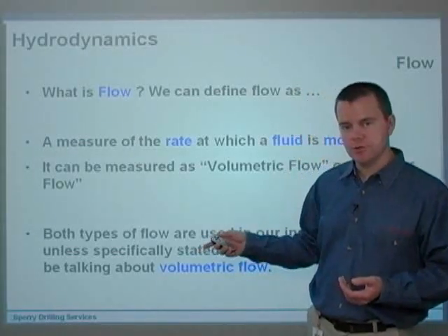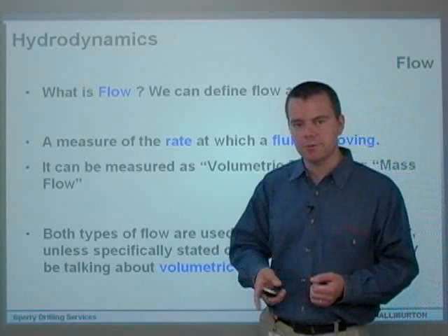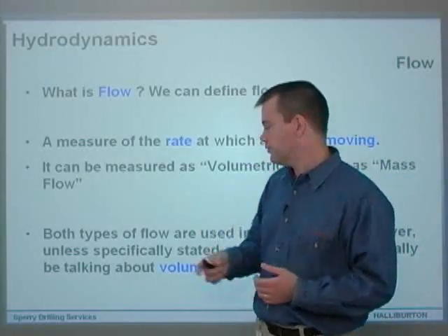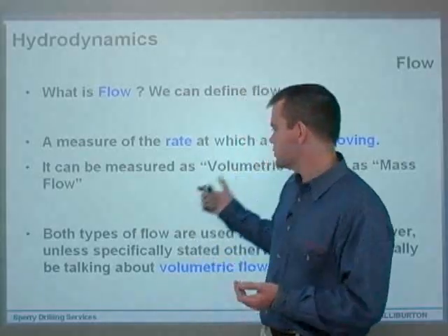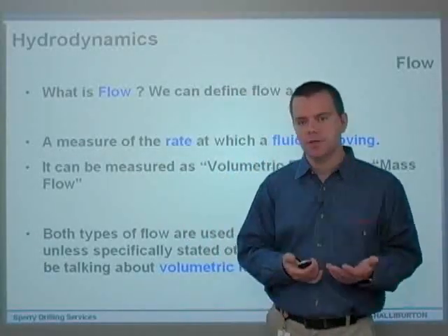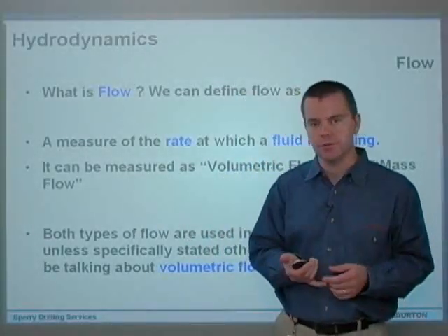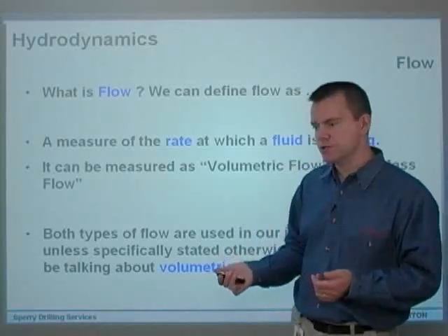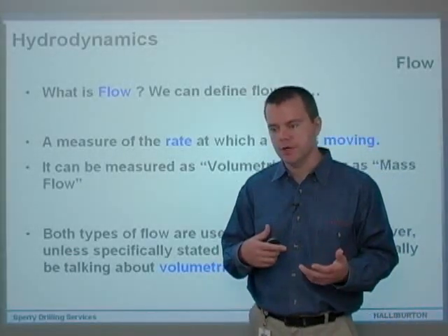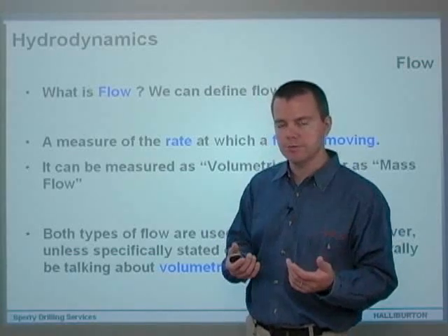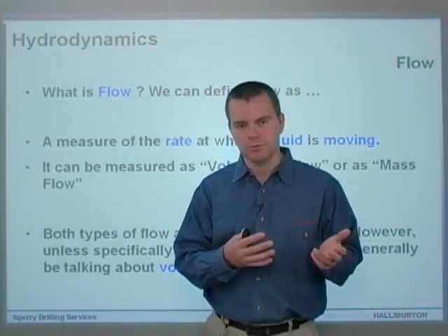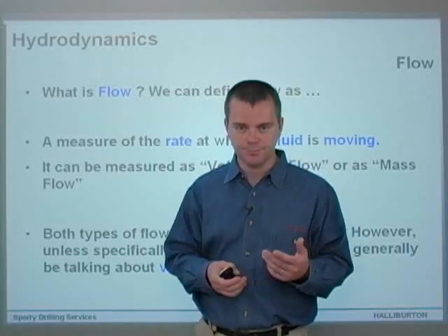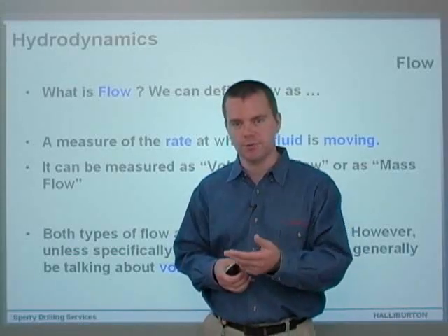Most of the time during this course, I'll be talking specifically about volumetric flow, unless I refer to it as mass flow. Places you might find mass flow are when you're flowing gases through pipework. You tend to talk about mass flow rather than volumetric flow. When you're looking at the spec sheets of an MWD tool, you'll see the maximum flow through that tool quite often will be referred to in mass flow units rather than volumetric flow.